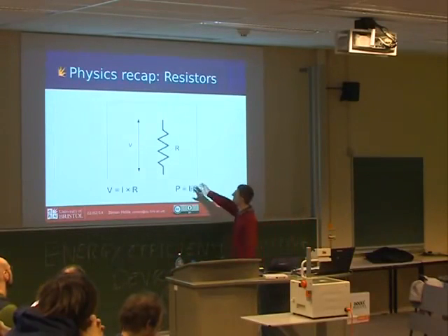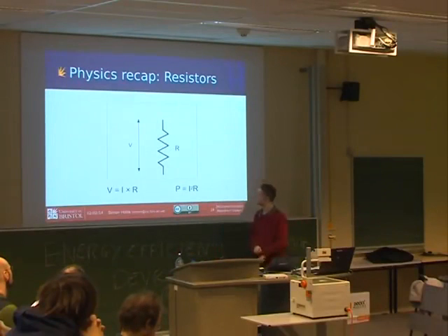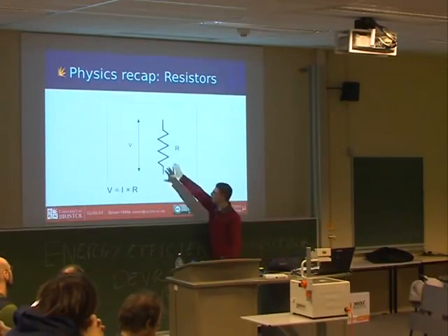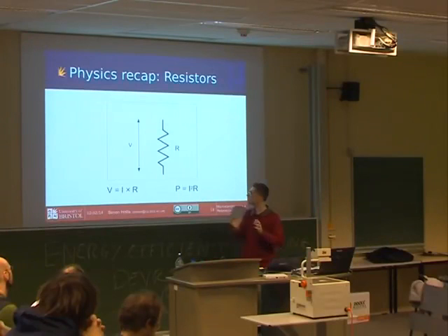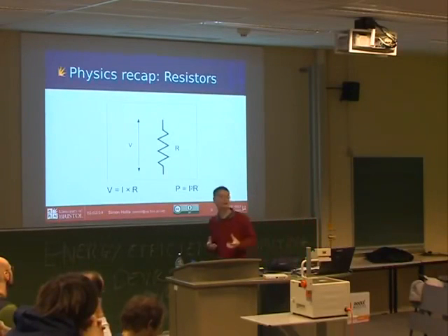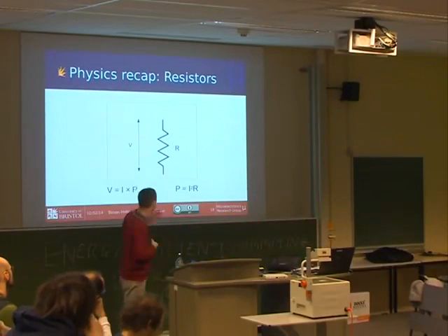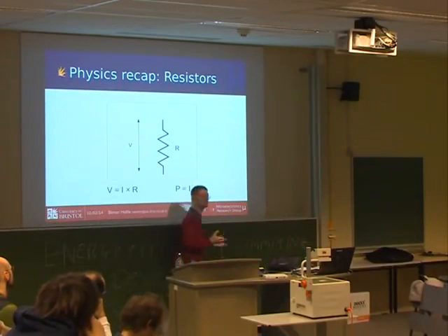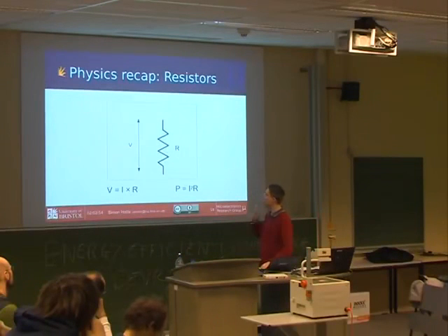And the reason it contributes power is if we just look back at Ohm's law and Joule's law, we had a voltage across the resistor, that was the channel, and I had a resistance, and therefore it dissipates power. And that power is squared. And this is one reason it's so good to shrink computer chips. When you shrink computer chips, you can reduce the current going through, which reduces the power consumed. So that's one effect.